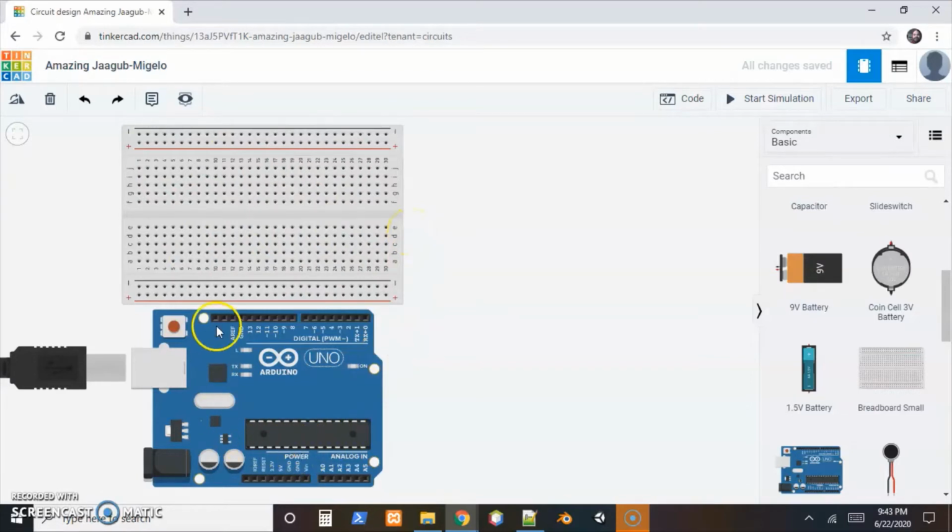Our microcontroller down here, you can see the labels here. The numbers up on this side represent our digital outputs or inputs. And basically, it's just a high or low voltage, a 1 or a 0. We tell the processor that, maybe for this pin here, we want to apply a high voltage to that pin, or we want to take away the high voltage and have a low voltage. Basically, we have either a 0 or a 1 at that pin. We tell the processor that.